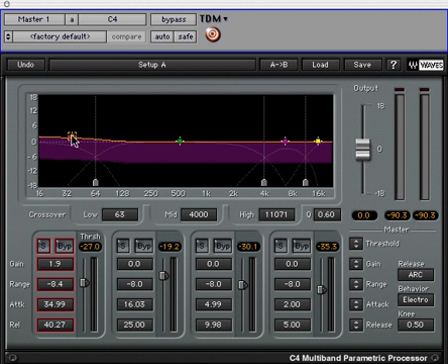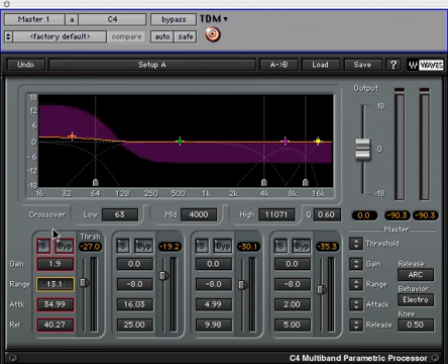The individual 4-band controls are underneath the main display area. Each band has a solo button shown as S, allowing you to listen to each individual band post-processing. Next is the bypass, allowing you to return the selected band to unity gain without processing. The range dictates the maximum gain change for each band. Negative values make it a compressor. Positive values make the band into an upward or downward expander. A setting of 0 has no dynamic change to the band, and C4 then can be used as an EQ.